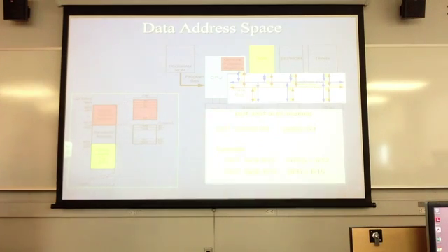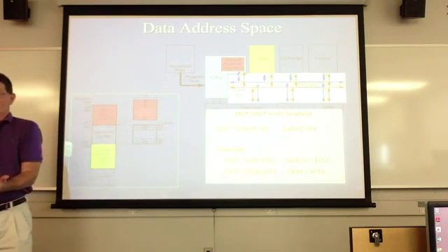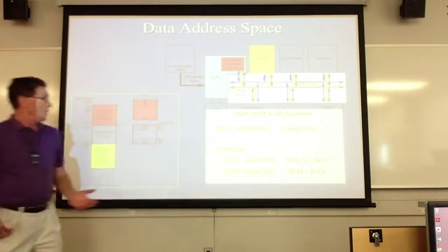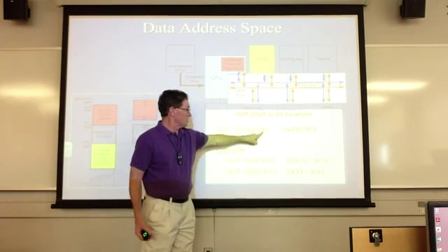All right. I can also write out to an I/O port. So if I need to physically write out to this I/O port, I can use OUT, give it the port address, and then give the register contents. If I'm going to write out to it, I need some data to write out. It could be the contents of a register.